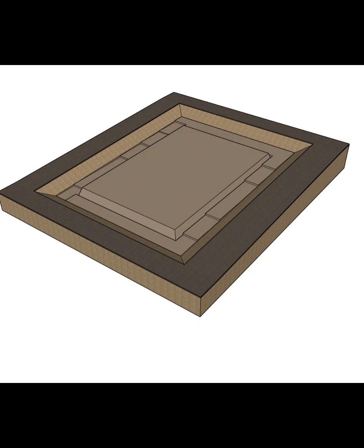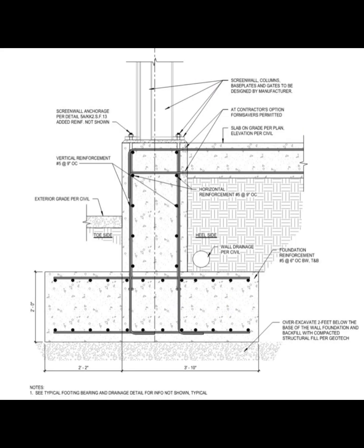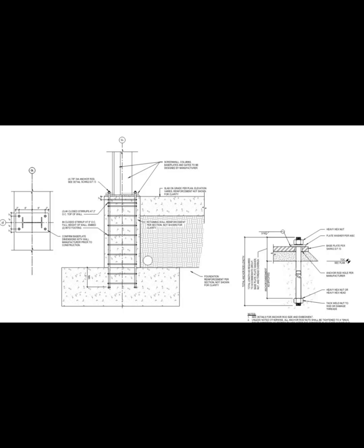Let's take a look at the foundation details. This is a standard stem wall on footing. The wall size is much thicker than usual due to encapsulating plinth cages for the screen wall columns. These plinth cages land on stepped footings, so care must be taken when installing the bolts to depth. The rule is bolts must embed 12 inches into the footing. This places the nuts between the bottom and top mats of the footings.